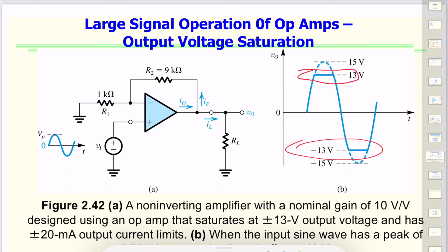That's the case for the 741 op amp, which has a maximum output current of 20 milliamps. And this is the range. So our design would not require more than 20 milliamps, and we have to play with the feedback and the load resistance to get to that value.